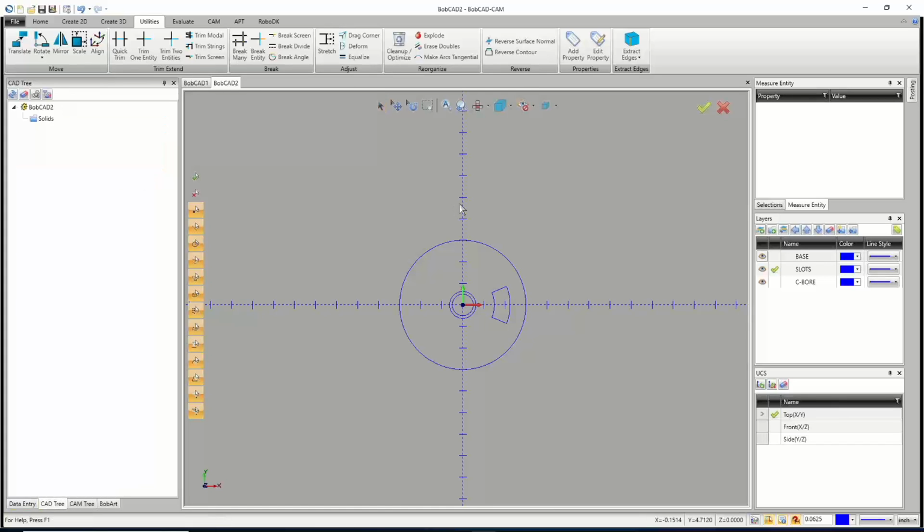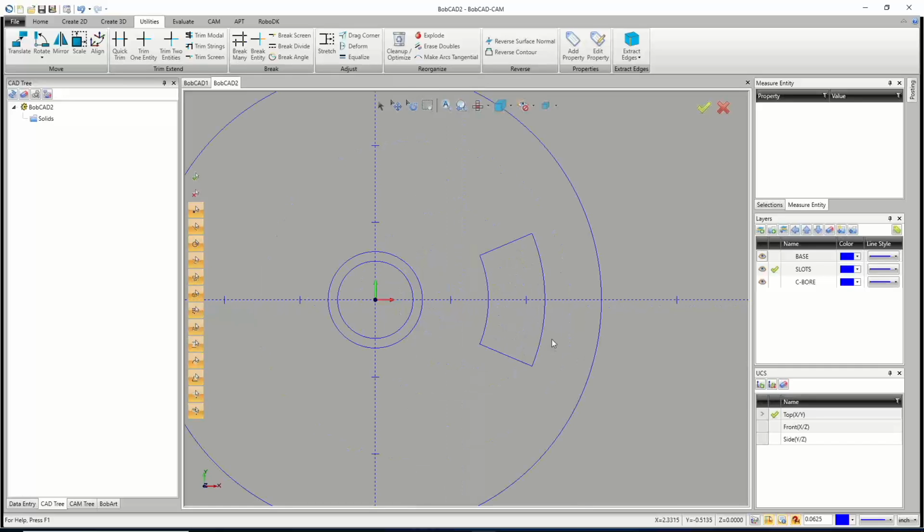Make sure you use it whenever you're working with your wireframe, especially if you're going to turn your features into solids. If you're going to start doing extrusions, make sure to do it beforehand, because if there's bad geometry on an extrusion, you'll get walls, but you won't ever cap the part off. If you don't catch it, you'll stitch things together, and it's a big mess you do not want to deal with. So there we go. The next thing I want to do is throw some 1/4 inch fillets on here. I'm sticking pretty much everything to about 1/4 inch, just because that way I don't have to go real small with the tools.